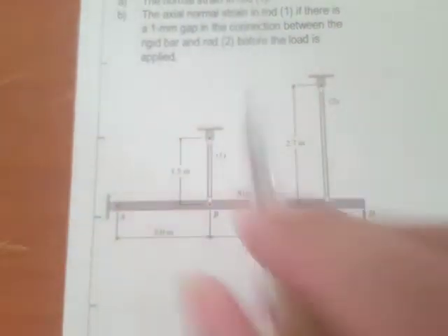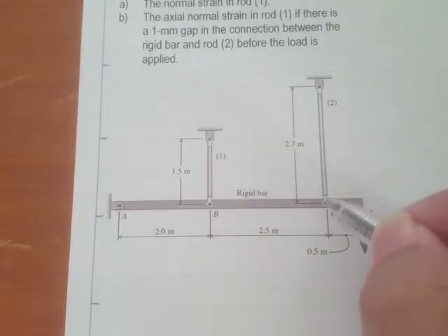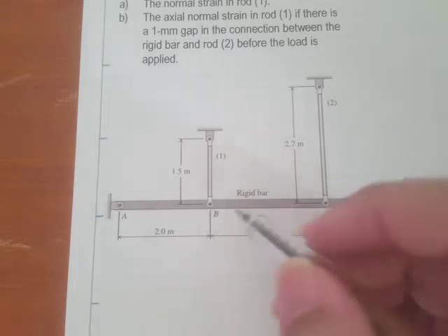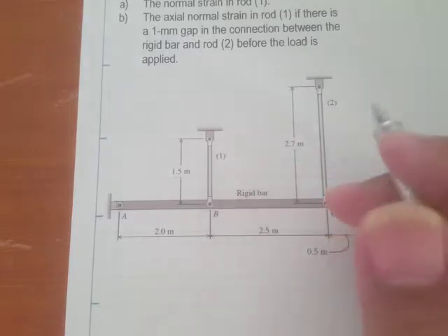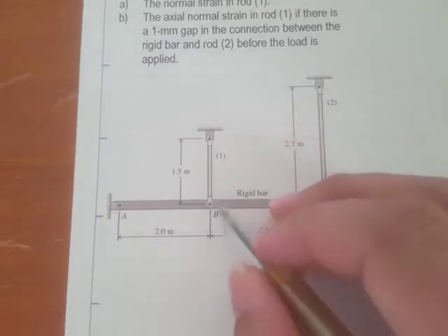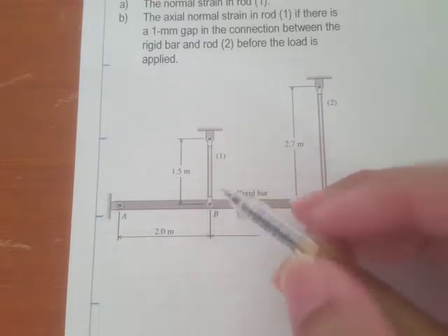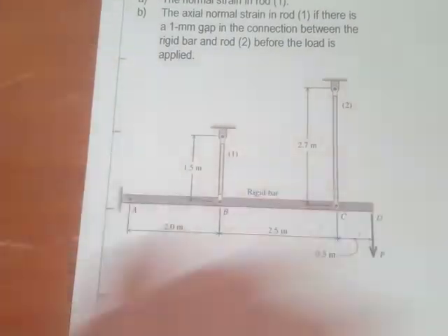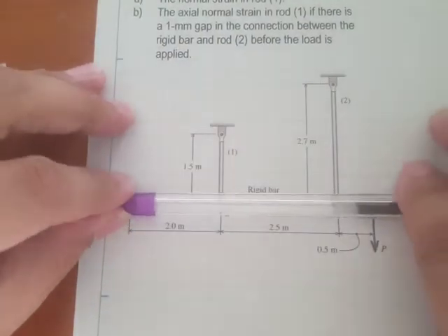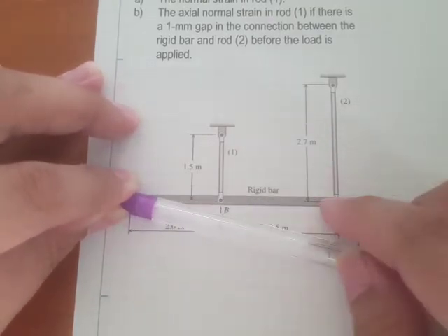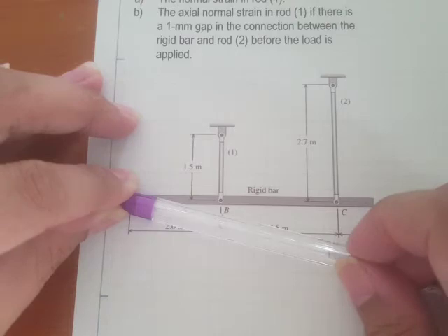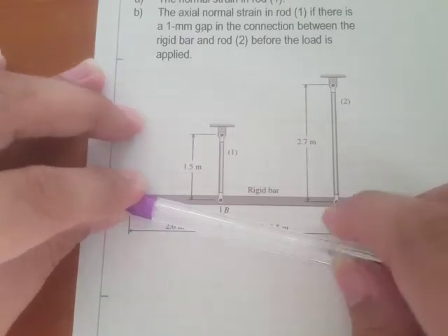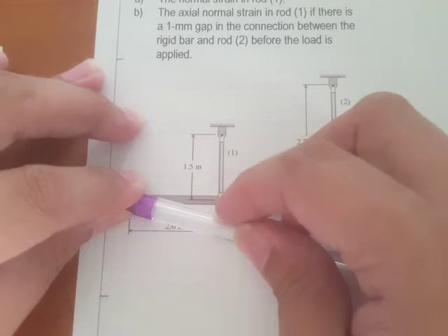First is the normal strain in rod 1. Okay, so this one is given in terms of strain, but the geometry of deformation must be expressed in terms of deflections. So once you have all this, and also once you apply the equilibrium case, then we can solve the deflection. What's going to be the deflection at this point B, right? So it's like this. There's a rod, so because of the load it goes down. So right here there is a strain value of 800 microstrains, and what's going to be the deflection or the strain right here at point B.